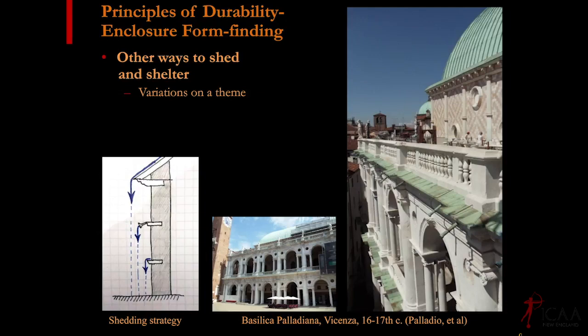These are essentially like a copper scupper, what the Italians call a doccione, which means big shower. And when it discharges all the water off this balcony, it does turn into a big shower. And the important point is it's clearing it all the way to the ground, and it's not just dumping it on the level below. So again, very thoughtful design and a variation on that same general theme and general idea. So these are all about water management.